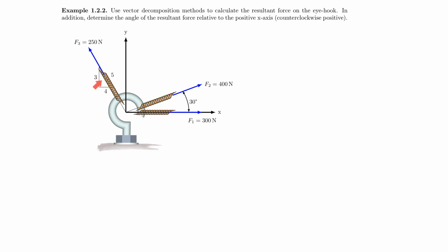So this is called the 3, 4, 5 triangle. And what students tend to do when they see this problem first is they try to convert this into an angle. They try to calculate the angle here and then figure out the components for this force. But I will avoid this now, and you will see that A, it is much faster and it saves a lot of time on my exam. And B, it's much more precise because I'm dealing with fractions.